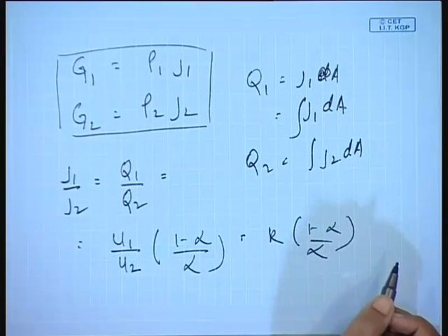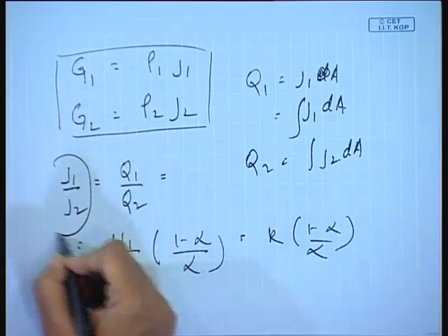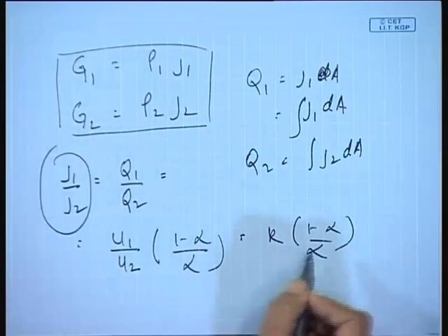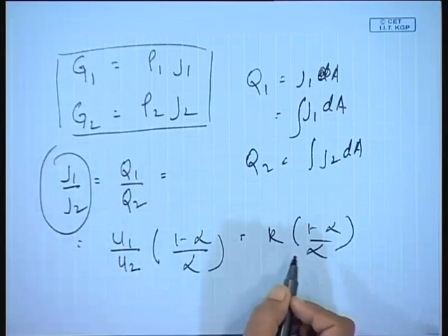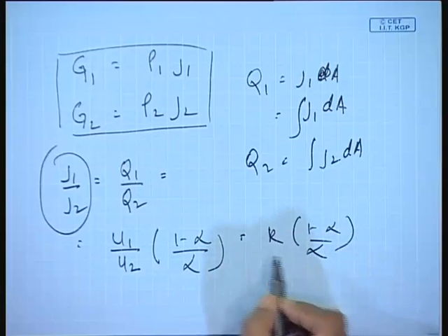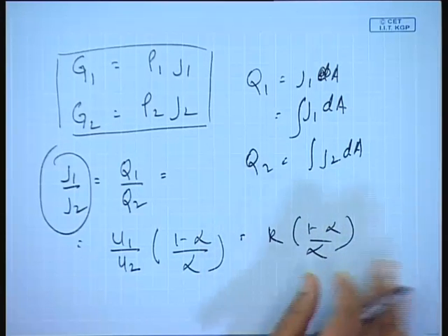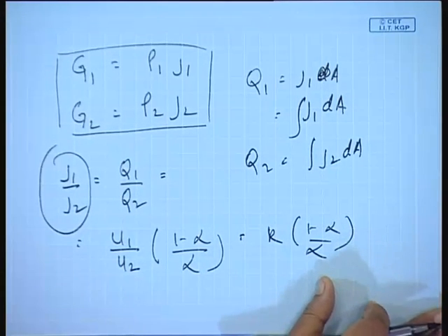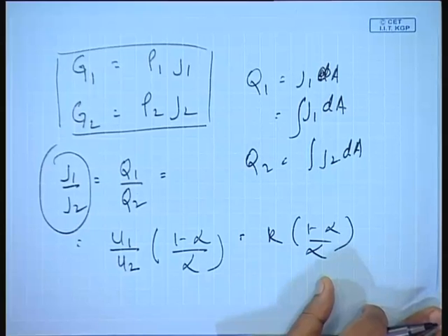Why are we trying to connect all these things? Because this is a measurable parameter. So, if data are available on alpha, we can find out k, or vice versa. Okay. Now, this was about the volume flux. Probably you have also heard two other terms. They come up just because of the different velocities the two phases have. These two are the drift velocity and the drift flux.